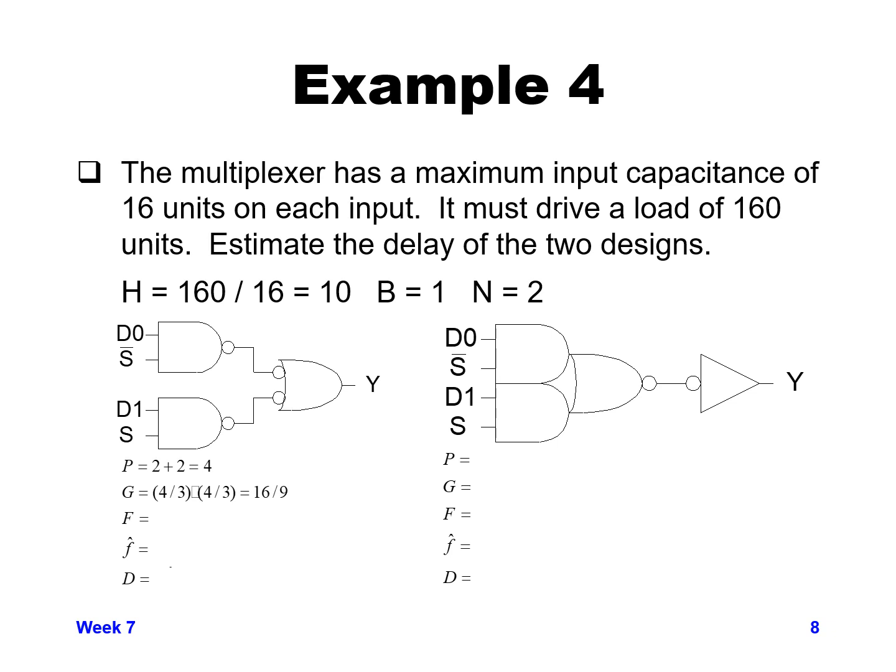Now the overall path effort is defined for a path as G times B times H. If you don't remember that, I'd recommend going back and reviewing last week's set of slides. G, we just calculated, is 16 over 9. B is 1, which we calculated at the beginning, and H we calculated at the beginning as 10. So we basically have 10 times G, so 160 over 9 is our total path effort.